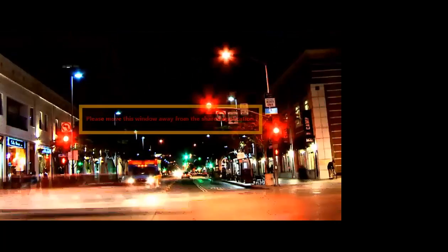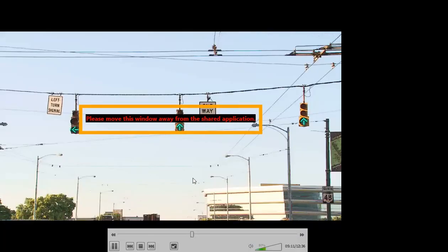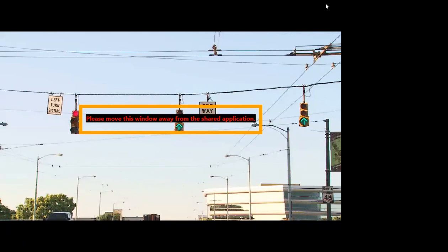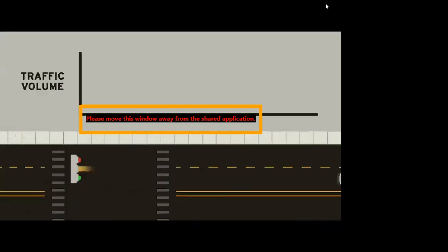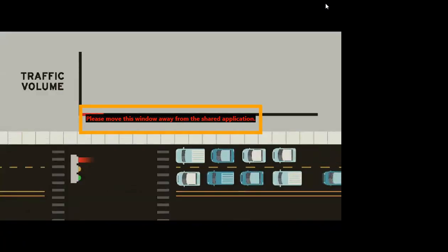There are an endless variety of phasing arrangements that traffic engineers use to accommodate various intersection configurations and traffic volumes for each movement. Even the simple decision of whether to use protected or unprotected left turns takes a significant amount of analysis and consideration. Another important decision is how long each sequence of a phase should last.